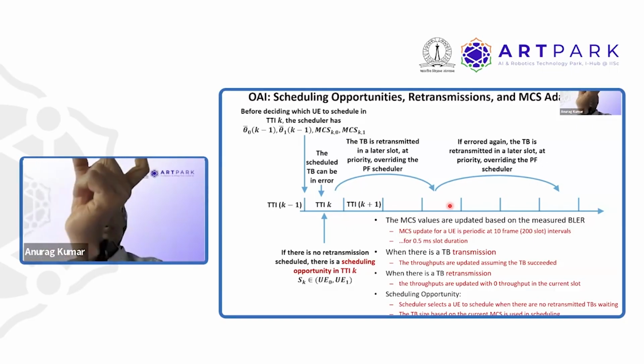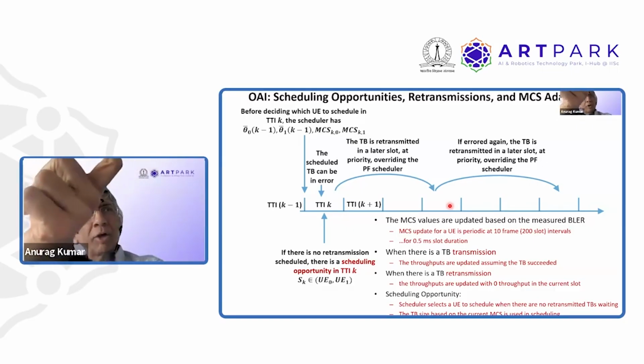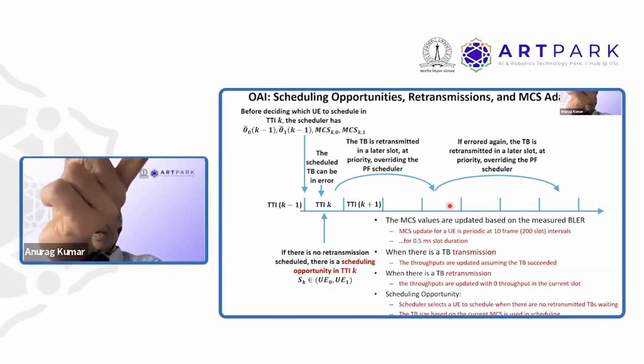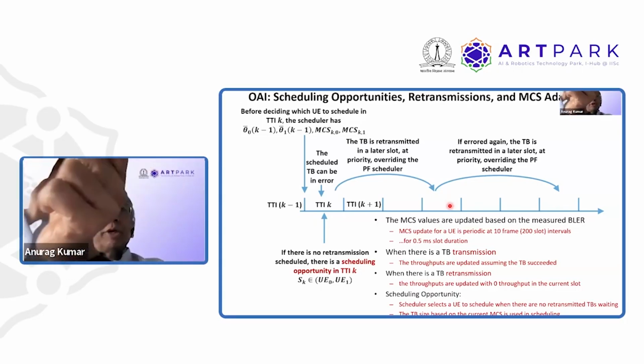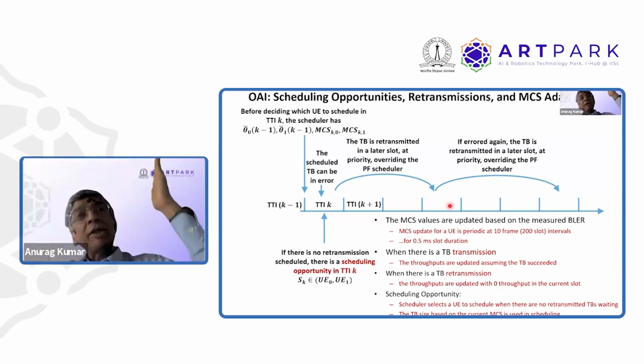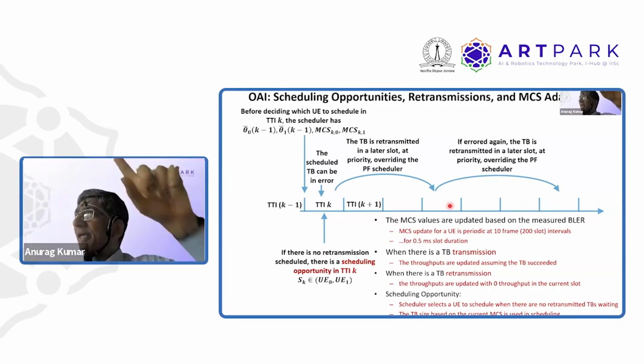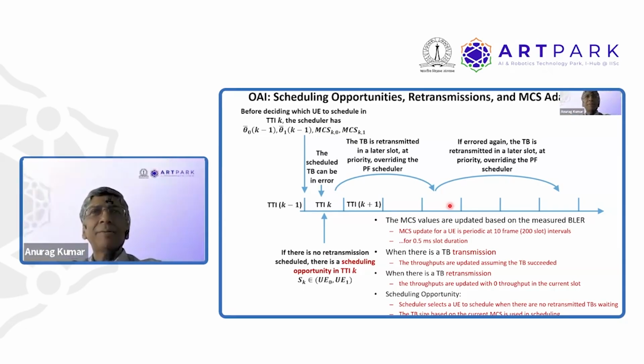So what it allows you to do is to break up a 0.5 millisecond slot into mini slots. And if a URLLC packet arrives within a mini slot, then you schedule it immediately. But at the beginning of the slot, you already scheduled an eMBB frame. So the way they do it is they actually take away some resource from the eMBB frame.